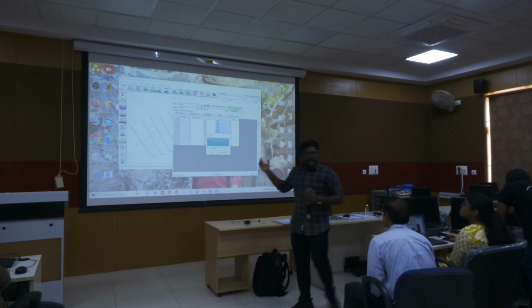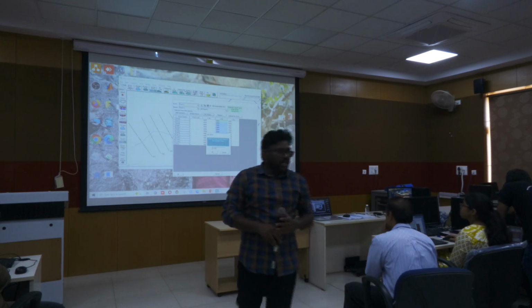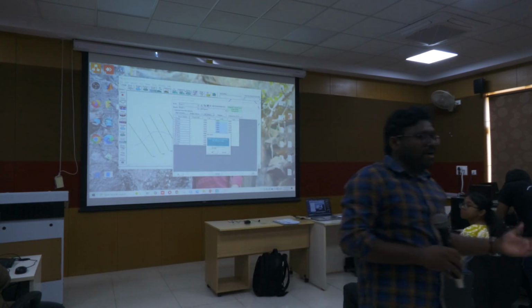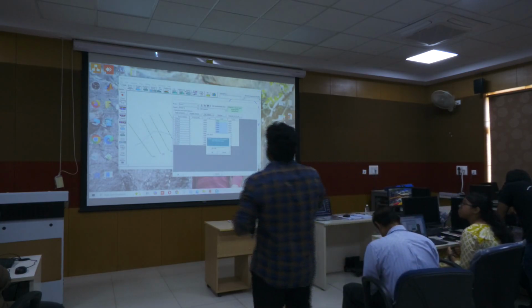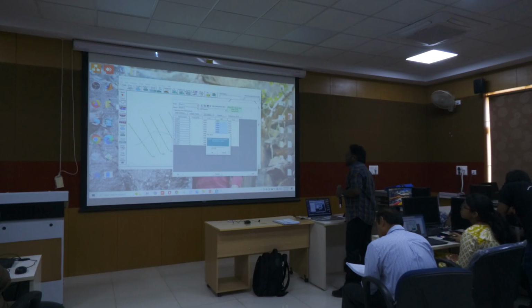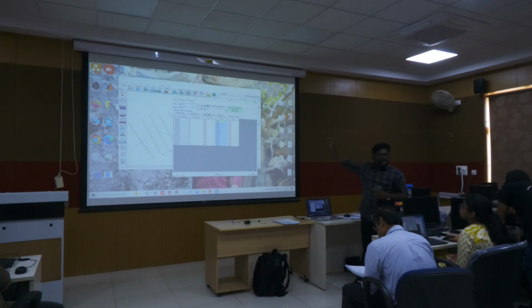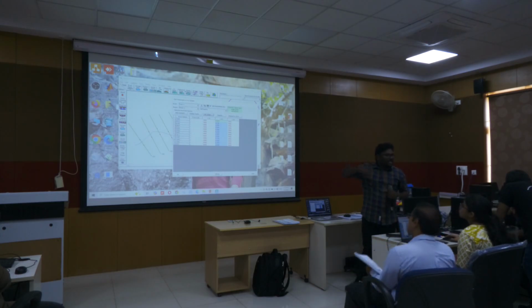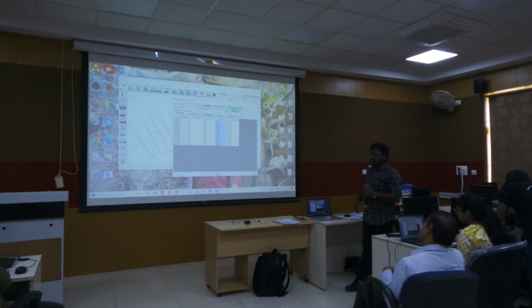You can give any number, but it should be smooth compared to the floodplain. So in the main channel I am giving 0.035 and click OK. So now it will assign the same roughness to all the cross sections in the main channel. Okay?